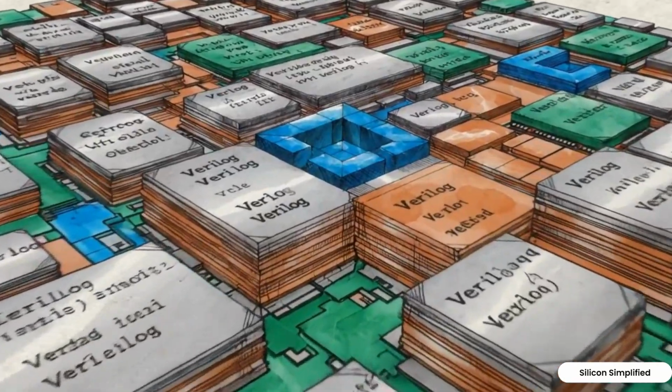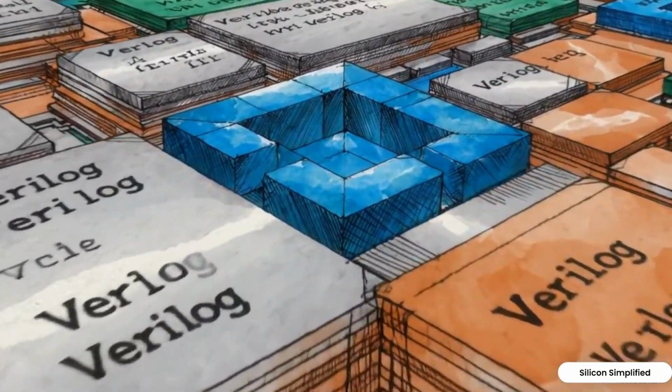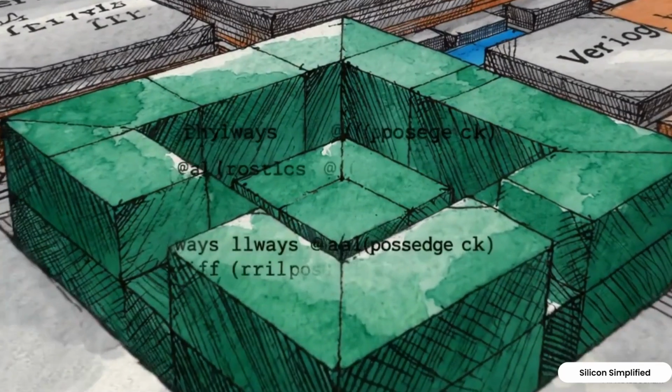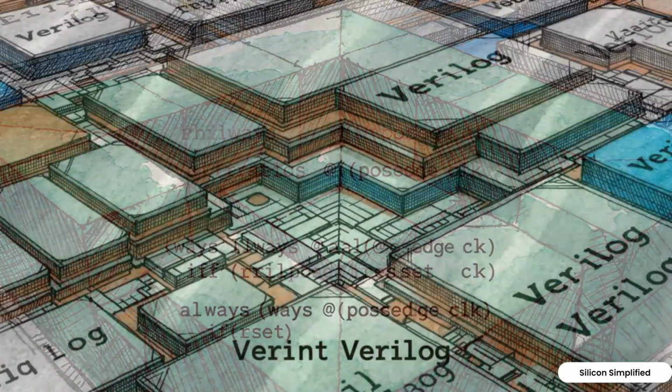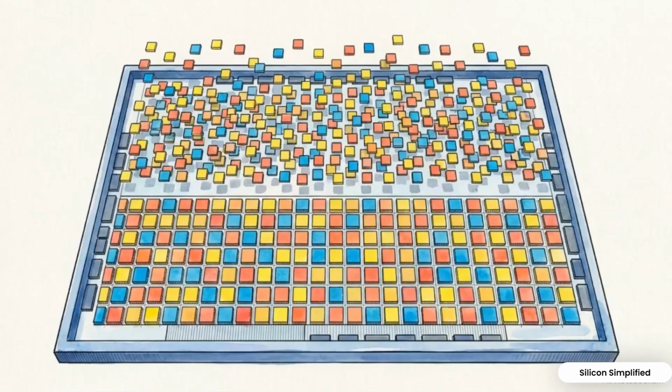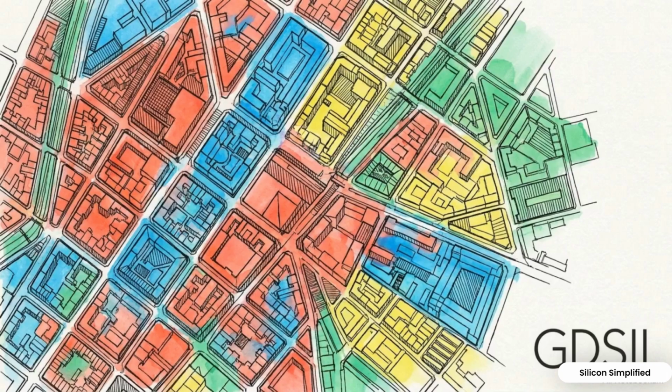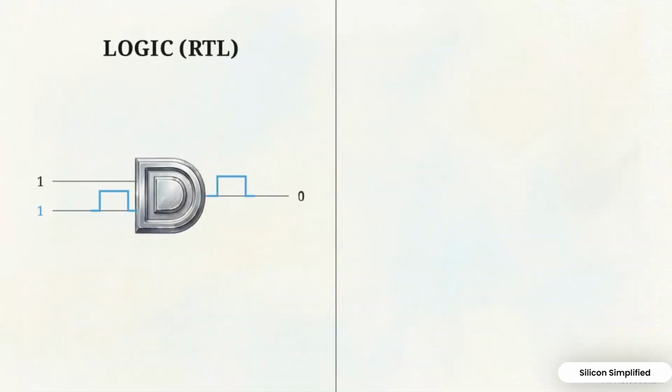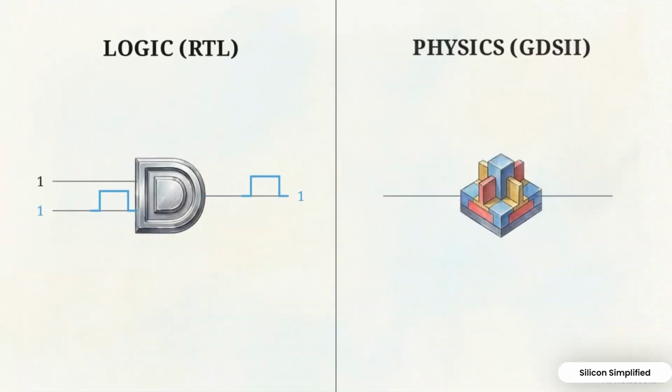The physical design flow is the engineering pipeline required to translate a logical, text-based chip design into a physically manufacturable layout. This process involves the precise mapping of billions of individual logic instances onto a constrained silicon die. The final output is the GDSII file, the industry-standard geometric database containing the exact polygons sent to the foundry for fabrication. In a hardware description language like Verilog, a transistor acts as a mathematically perfect switch.